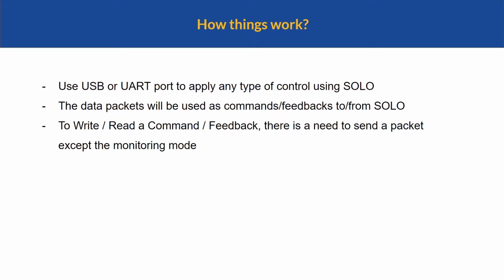How do things actually work in digital control of Solo? First of all, you use USB or UART to apply any type of control that we did before using the analog port. We normally send data packets, which are used both for commanding and getting feedback from Solo. In order to write or read something from Solo, in any case, you need to send a packet. Either you set something, so you need to send a packet, or you request to read something. In either case, you need to send a packet.